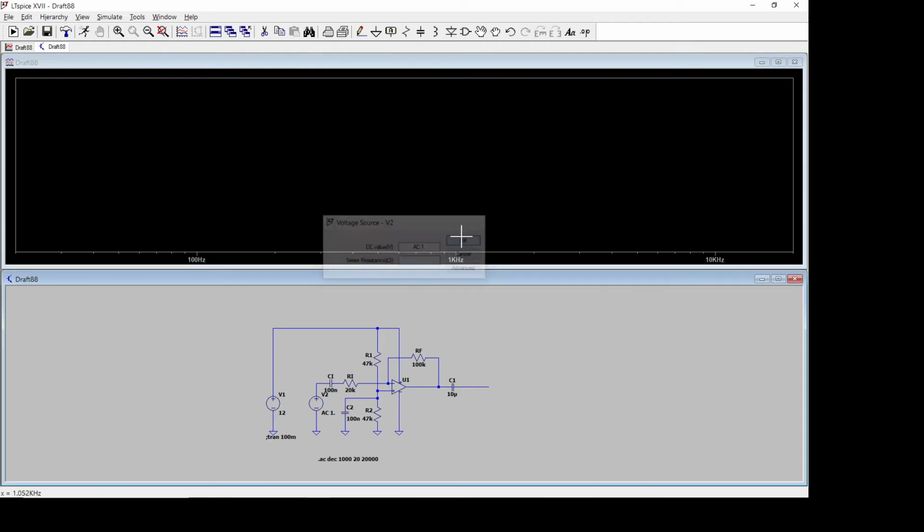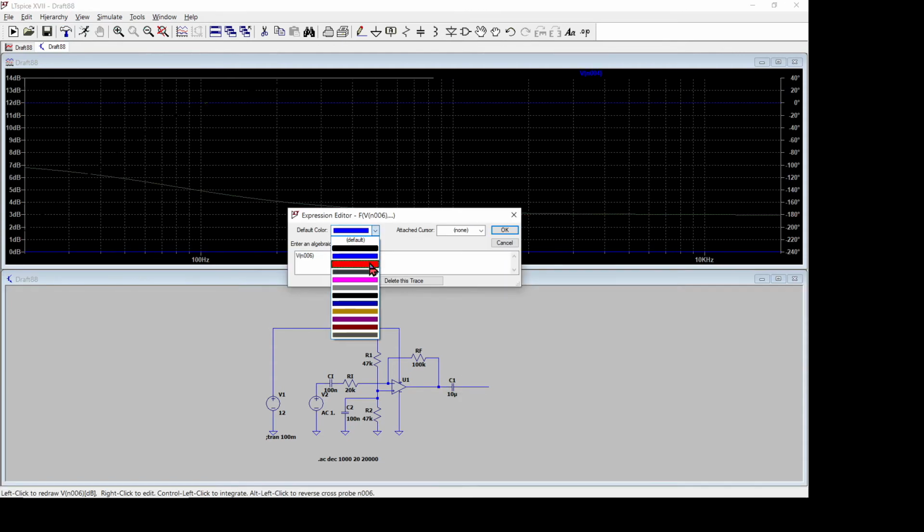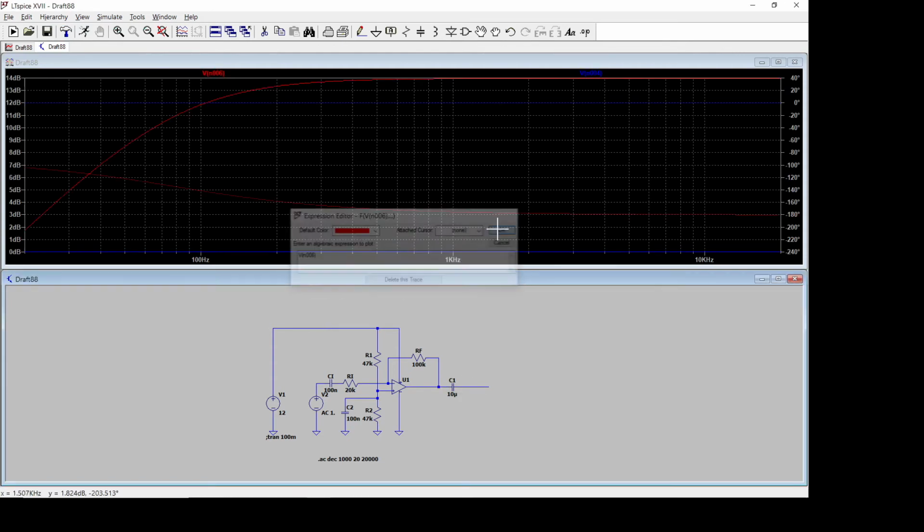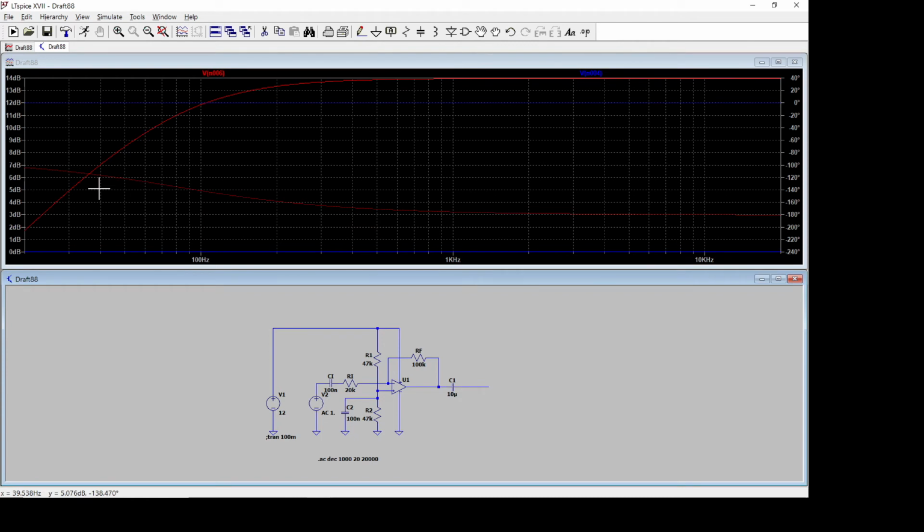We can see that our simulation result shows a frequency analysis of our preamplifier voltage gain. At low frequencies, amplification is low, and at high frequencies, amplification is higher at plus 14 dB. As usual for an audio amplifier. You could set the cutoff frequency with the input capacitor Ci.